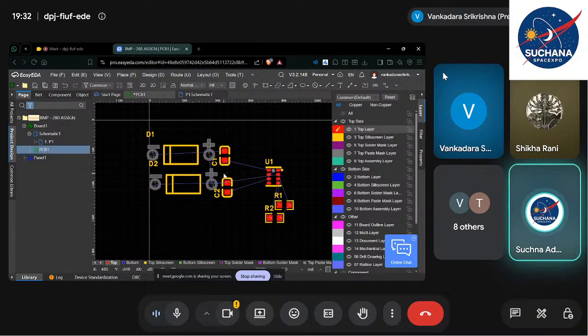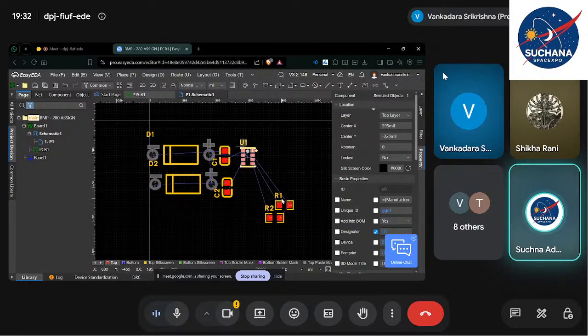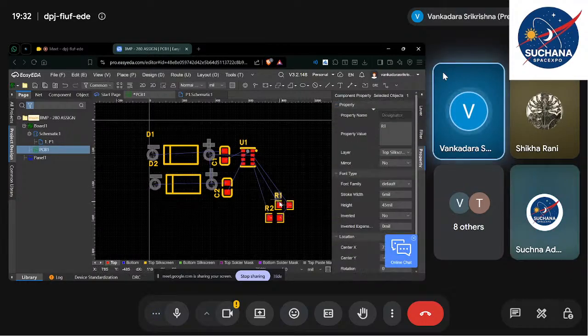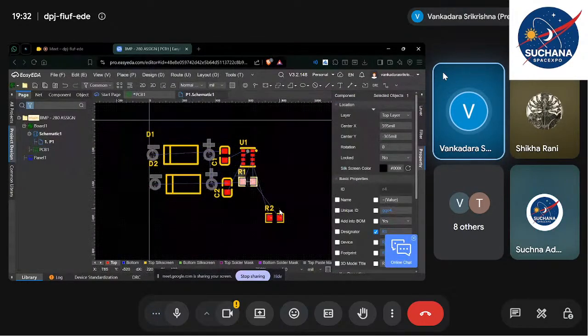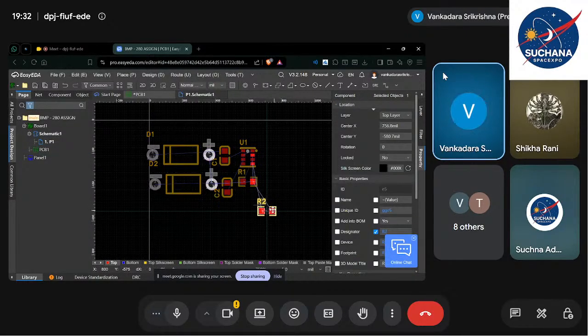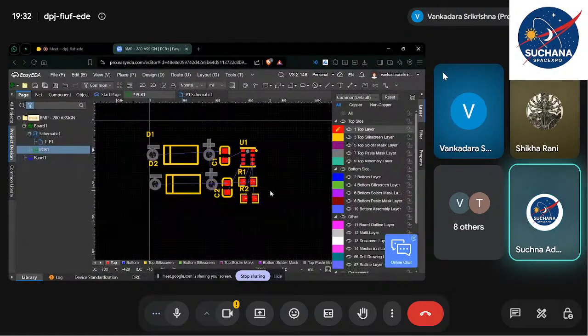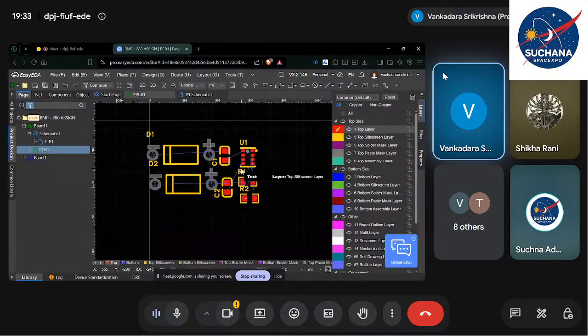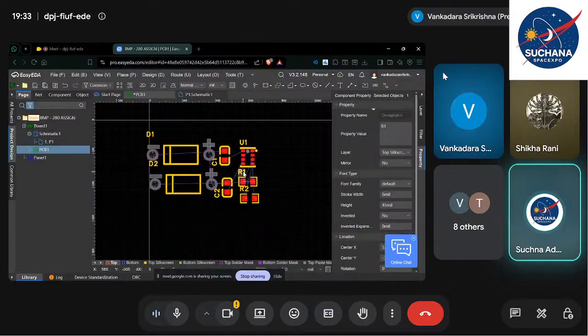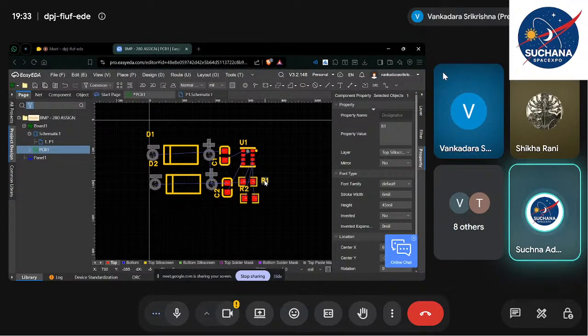So now see designators. Few designators are facing one direction, few are facing another direction. You also need to fix that. Now do one thing. For resistance, there's a designator, right? Try to move that designator position, the R1 position. Yeah, put it in front of the resistor. You just orient it. Okay, that's also fine. It's also allowed.